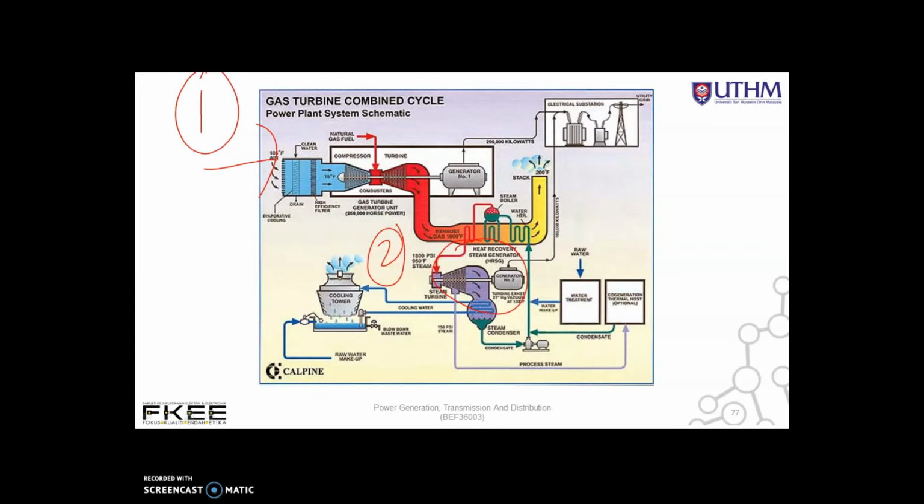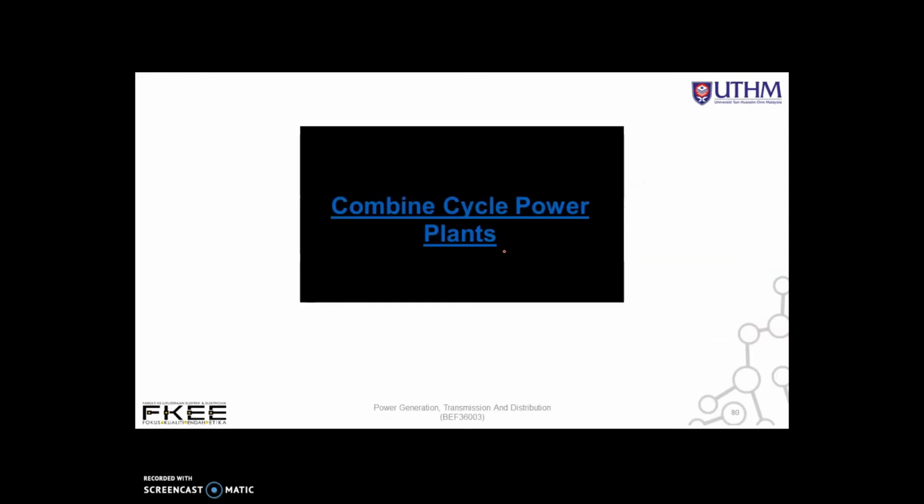Combined cycle power plants, CCPP, may employ one or several gas turbines. So we have this one turbine, and a second turbine. Each gas turbine is equipped with its own waste heat boiler designed to capture the exhaust heat as efficiently as possible. The most efficient plants will employ gas turbines, the heat recovery steam generator HRSG, and steam turbines that have been matched to one another, incorporating all those things together. CCPP can be based on modules of around 300 to 400 megawatts, and the actual output can be increased by adding some additional heat generation within the HRSG, a procedure called supplementary firing. This is the explanation; this is the video that I will share with all of you later on.